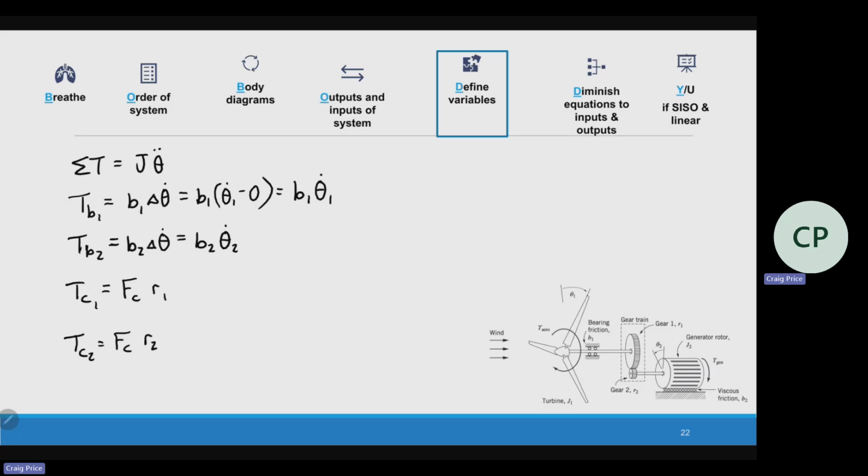Based on the picture, which torque is greater? Larger gear, right? The more radius you have, the more torque you have. Which one of these has a higher rotational velocity? Yeah, the smaller one is going to be moving faster. And that's why they set it up this way. They want the generator to spin more than the turbine, because that's where the energy creation is happening. Good?